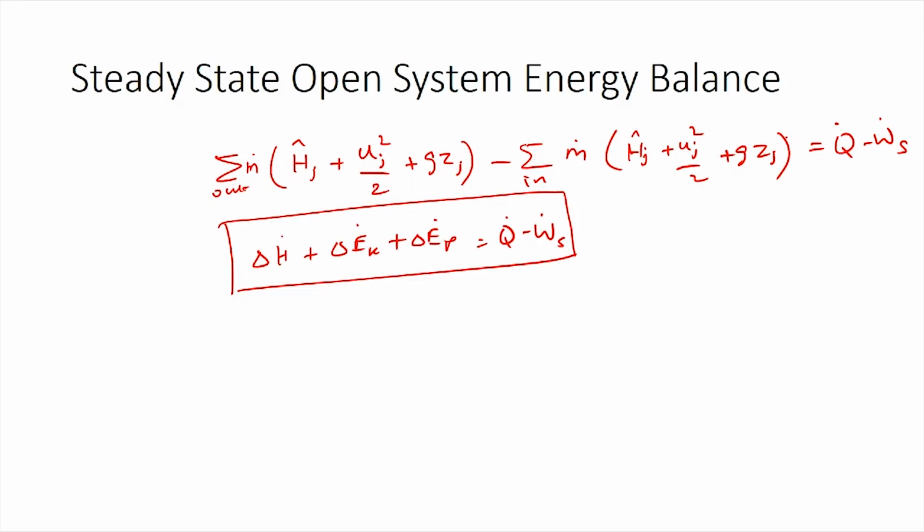What we need to understand here is, for a closed system, energy balances are performed using internal energy, and for open systems, energy balances are performed using enthalpy. This is because the flow work associated with the flow of a material in and out of the system is accounted for by using enthalpy. So, internal energy plus this flow work ends up becoming enthalpy in the mathematical expression. Therefore, we use enthalpy instead of internal energy while we perform energy balance calculations for an open system.